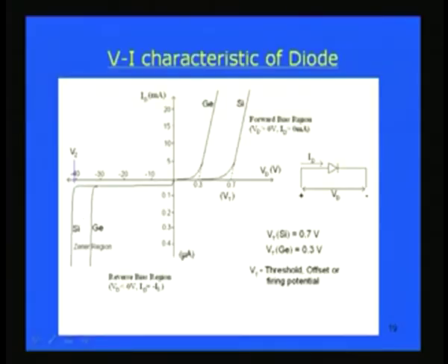The power dissipation capability of the diode should be very high. Under normal diodes, if we apply a very high reverse bias potential, then it may not be possible for the diode to sustain that high power being dissipated. So, you generally do not apply such a high potential to a normal diode, and for that particularly Zener diodes are used, which can withstand this high power.